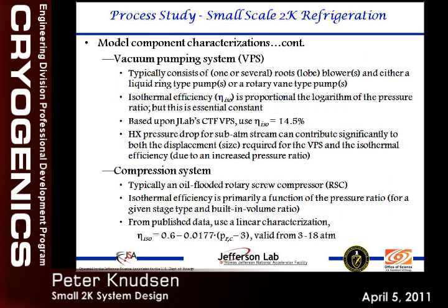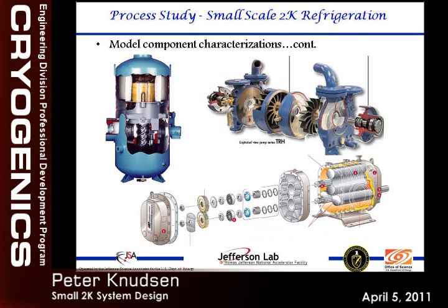This is basically the equation we're using to model the thermal efficiency for that compression system. So you can see it is a function of pressure ratio. This is a picture of some of the components, not all of them, but this is a rotary screw compressor. It used to be known as Dunham-Bush. It's now Hartford that is the name on it. That's a twin screw oil-flooded screw compressor, and it's hermetically sealed.